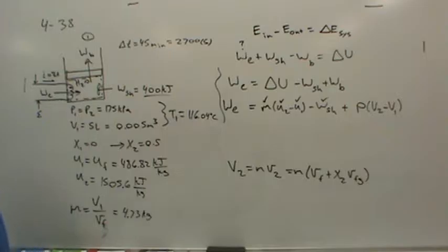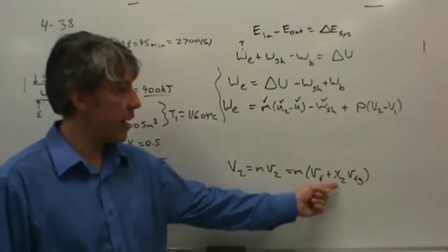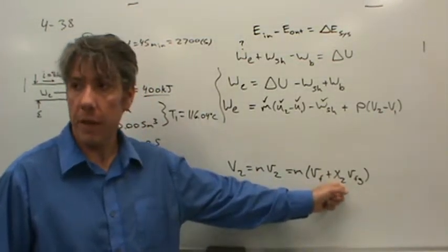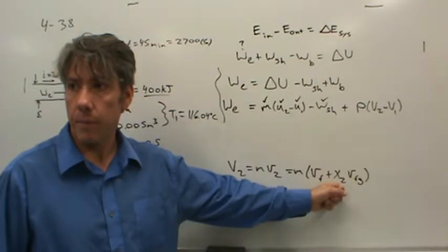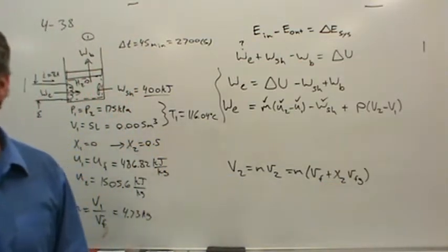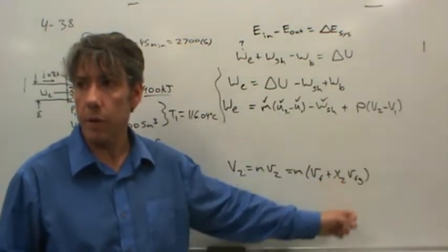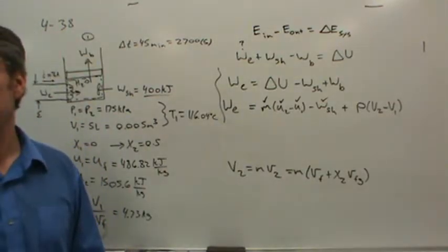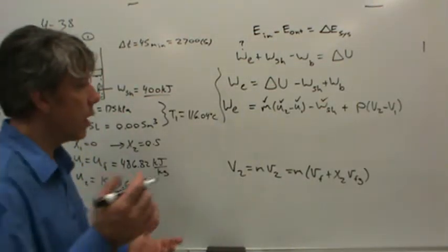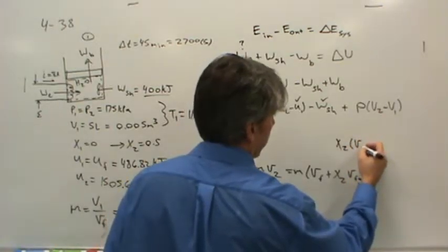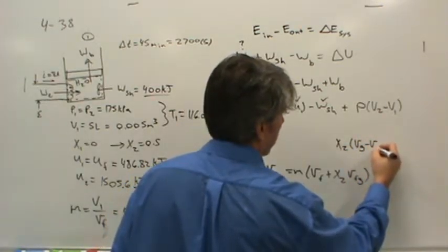Okay? So half the mass evaporated from that, half the mass is in the vapor phase. That's right. So that's where the 50% is going to be right here, X2. I was thinking just M over 2 times... Right, I understand, and since it's a half, it would work. But when it's not a half, you need this form of the equation. It's more convenient. Now, if you want to figure it out intuitively and say, why is this working? Well, the quality in state 2 multiplied by the specific volume of vapor less the specific volume of liquid.